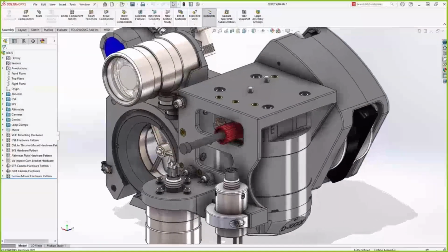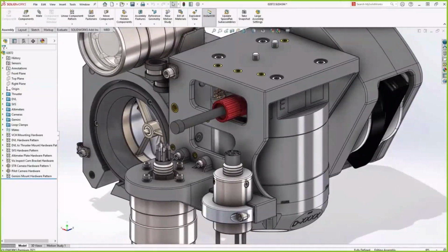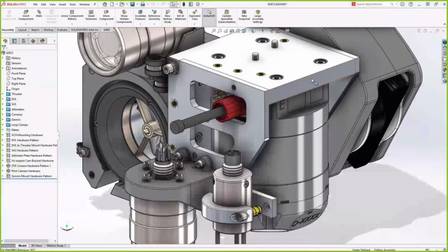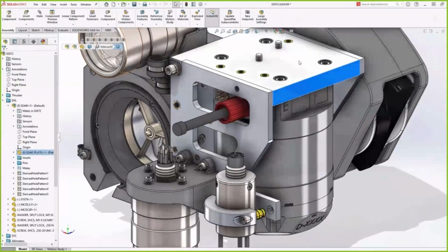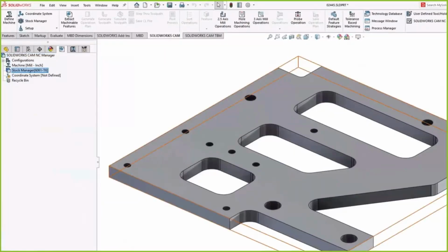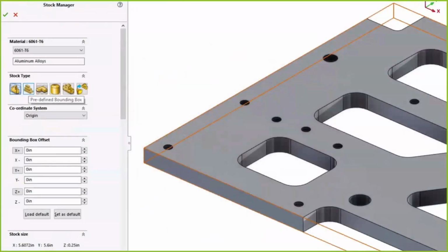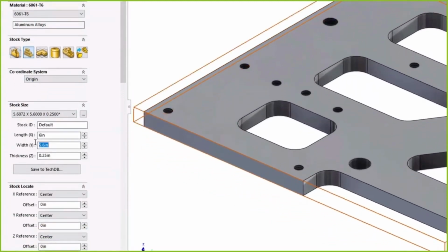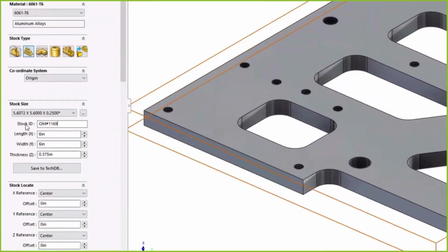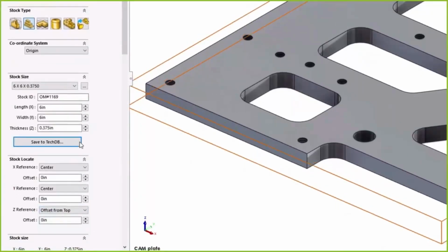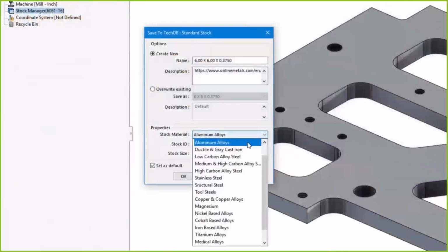As your production scales, you may need to expand your capabilities to include manufacturing. So to demonstrate the new amazing CAM functionalities in 2021, we're going to be redesigning this sensor mounting bracket. You can see on here that a default stock bounding box fits perfectly to our finished part. What's new this year is a predefined bounding box, which gives you the ability to represent standard rectangular stock. For example, this 6x6 inch piece of 6061 aluminum bar stock.